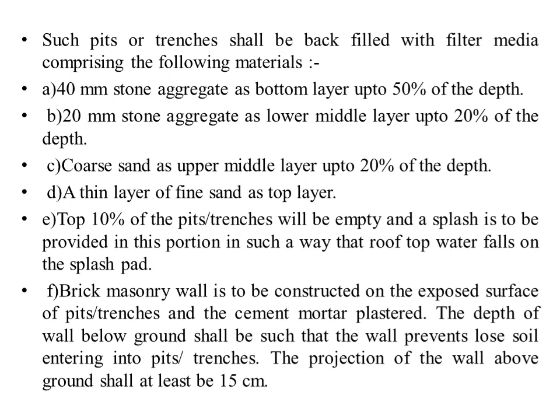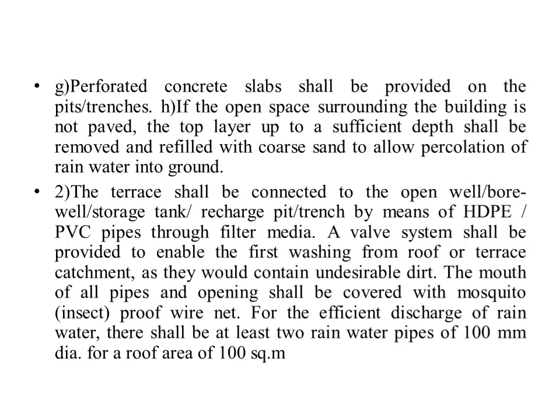rooftop water falls on the splash pad. Brick masonry wall is to be constructed on the exposed surface of pit or trenches and cement mortar plastered. The depth of wall below ground shall be such that the wall prevents loose soil entering into the pits or trenches. The projection of wall above ground shall be at least 15 centimeters. And then perforated concrete slabs shall be provided on the pit or trenches.